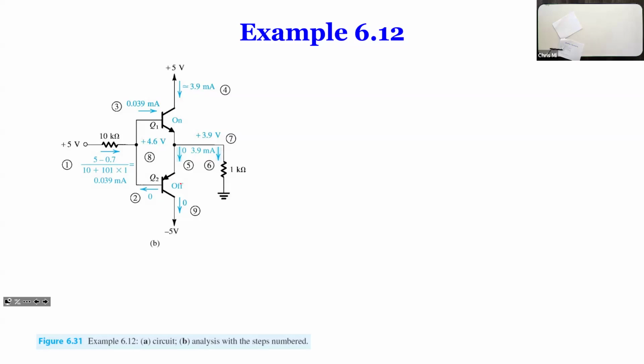What would be the threshold when we bring our base down to a certain value so that Q1, Q2 switch? Oh, you mean for what VB? Well, we have to calculate it. Apparently, if you bring that VB to minus 5 volts, you definitely would switch that too. If it is in the middle, you can calculate it.